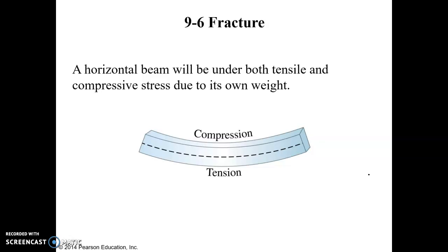Another potential failure mode for materials when a load is applied to them is bending failure. And this is essentially what I was talking about with a column. If you've got a tall, slender column, if I draw a little rectangular column here, its most likely failure mode is actually not going to be crushing, but buckling. It's going to bend out to the side.